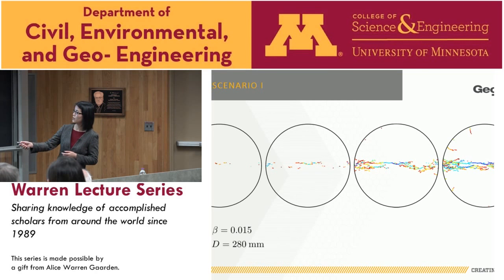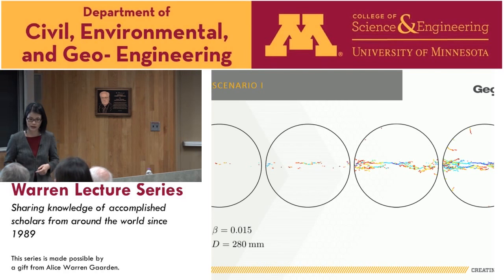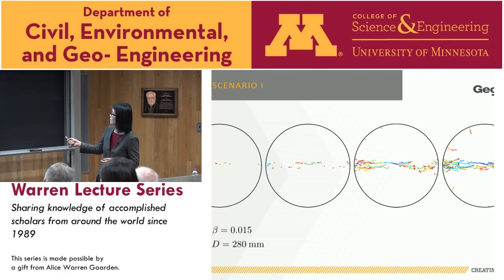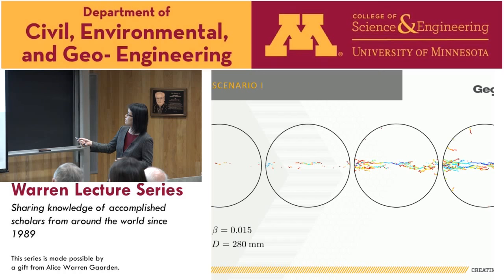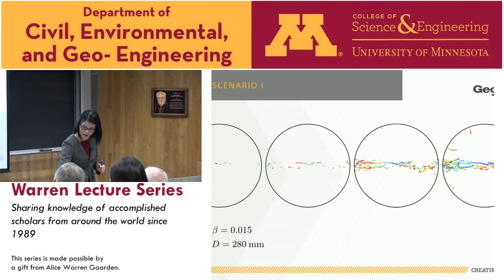The load is increasing in this direction. You start with a center crack, and then it develops near, because here it is highly sheared, so the crack cannot just break through immediately. It will start to develop these crack bands, and then the band width increases, and you also have cracks growing from the outside towards the center. And this is already slightly post-peak. This is around the peak time.